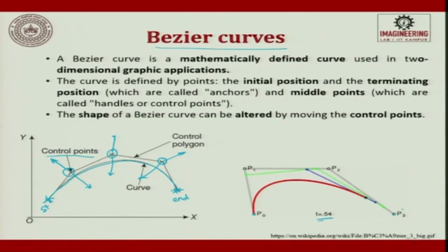Now you see I am establishing various control points by just changing the parametric value from t equal to 0 to t equal to 1. You see how beautifully it follows. Now it is very clear, I have to use start point, end point, and I will define control points. These control points again go into parametric form such that I define a curve.